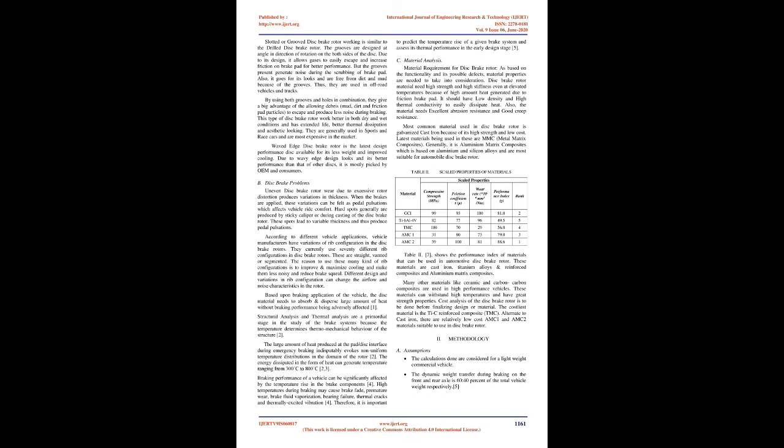Drilled disc brake rotors are used due to their increased surface area by drilling a number of holes in the disc. These drilled holes reduce the disc weight and increase the surface area to provide an escape route for friction pad particles, heat, and gases produced during braking. The drilled holes don't affect the structural integrity of the rotor and thus it is more effective for cooling the disc quickly. They are generally used for their looks and work better in wet conditions.